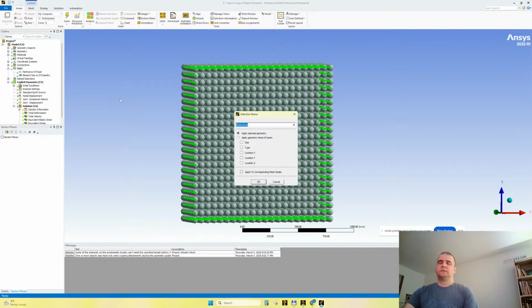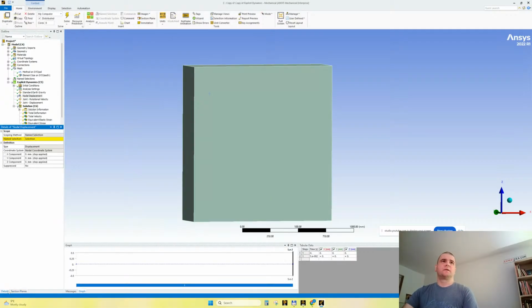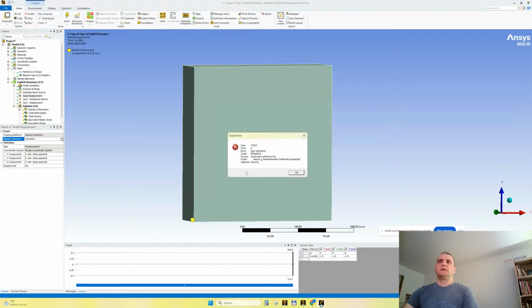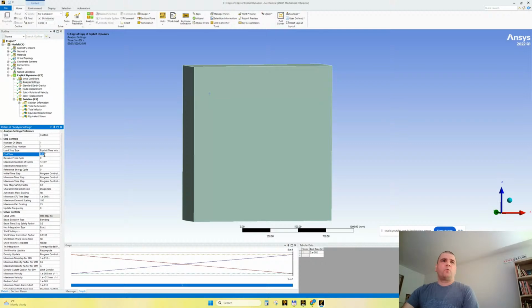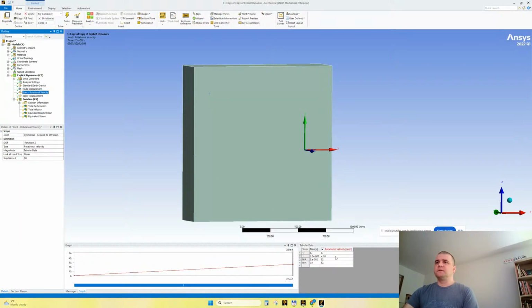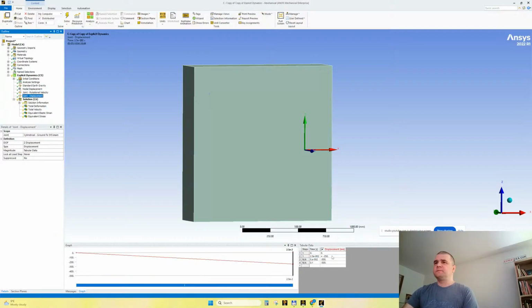And selection. And here we're choosing selection. All right. So I wanted to have here 0.025, the rotational velocity to be 150, and the displacement minus 300. Save.